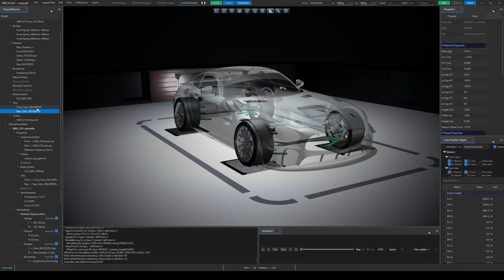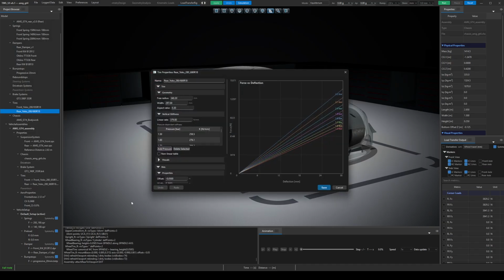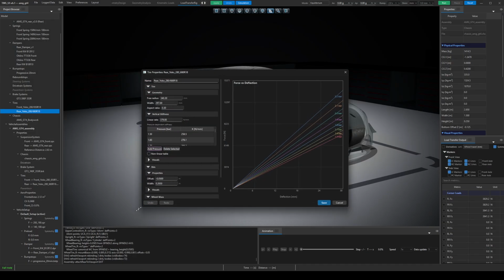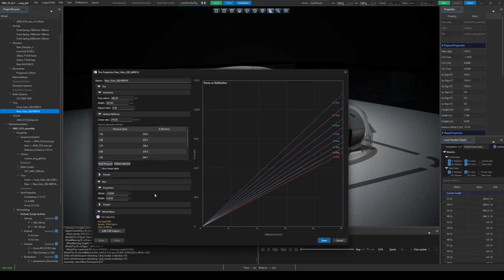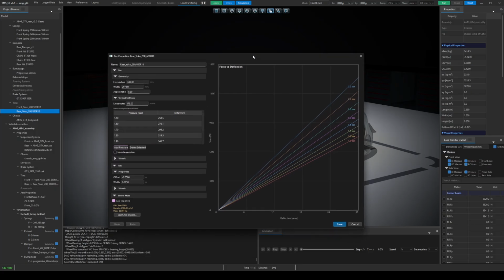Tire vertical stiffness can be represented either as a linear function, or as a table if the user has measured stiffness data at different pressures and camber angles. A possible workflow can start with something as simple as a setup pad simulation, predicting corner loads, ride heights after camber changes, how one alignment adjustment affects the others, and so on. Even this simple case, if done properly, can save a team a significant amount of time at the track.